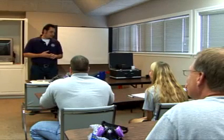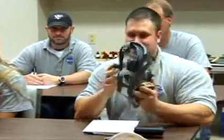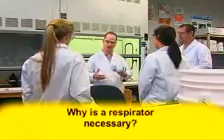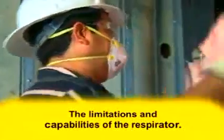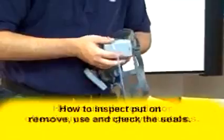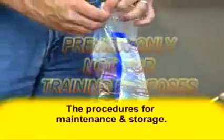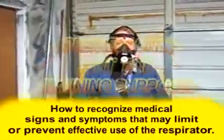Employees who are required to use respirators must be properly trained. Training must be comprehensive, understandable, and be repeated at least annually. Employees who are permitted to use respirators voluntarily must also be provided basic information and training on respirator use and care. Employees must be able to demonstrate knowledge of the respirator, including why a respirator is necessary and how improper fit, usage, or maintenance can compromise the protective effect, the limitations and capabilities of the respirator, how to use the respirator effectively in emergency situations, how to inspect, put on and remove, use and check the seals, the procedures for maintenance and storage, and finally, how to recognize medical signs and symptoms that may limit or prevent effective use of the respirator.